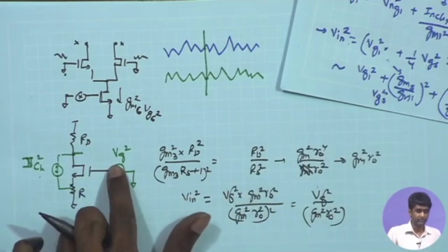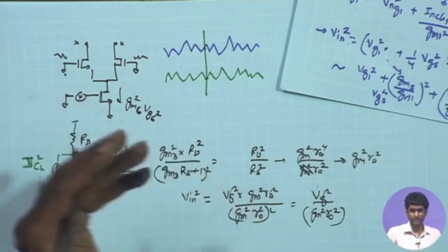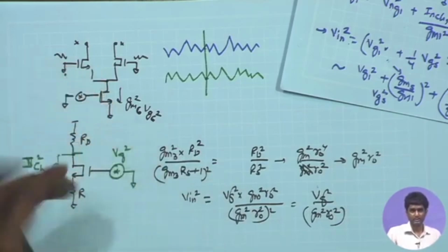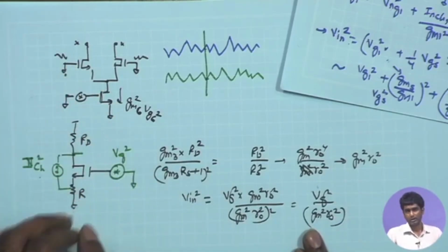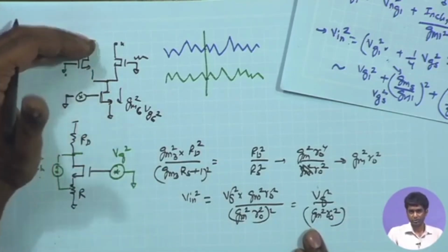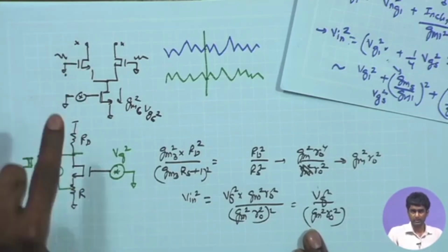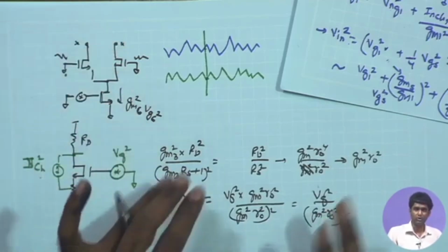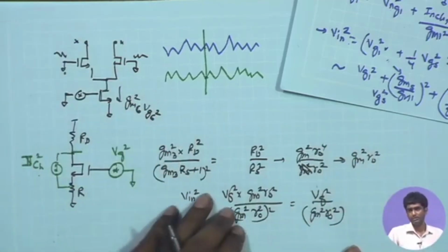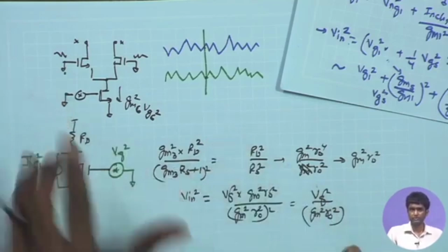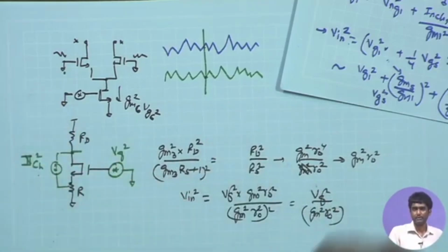If I am considering VG, it is getting multiplied only by gm RO, whereas the gate noise voltages of the devices connected to VDD and ground, in our case M2, M5 and M1, get multiplied by (gm RO) whole square, and as a result the noise contribution of these two can be ignored as compared to the noise contribution of M1, M2 and M5.